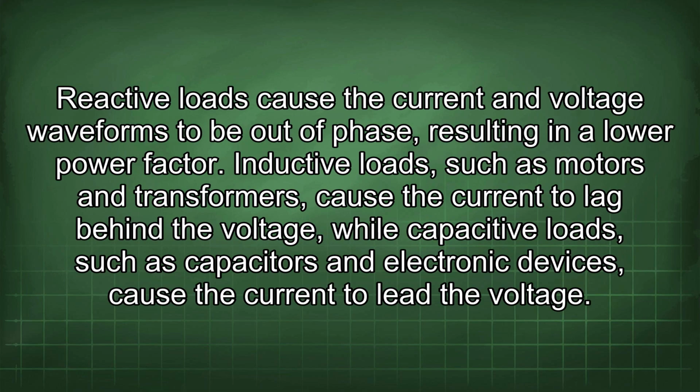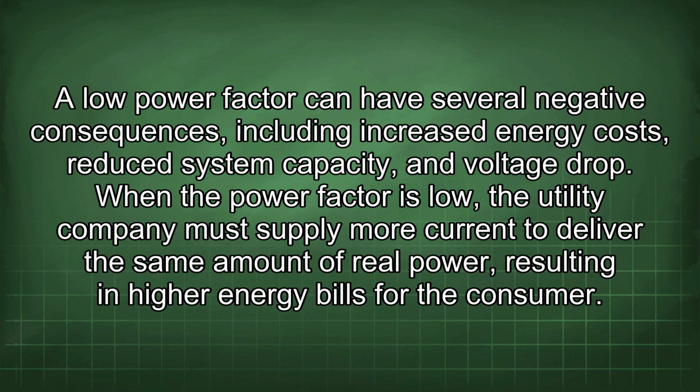Reactive loads cause the current and voltage waveforms to be out of phase, resulting in a low power factor. Inductive loads, such as motors and transformers, cause the current to lag behind the voltage, while capacitive loads, such as capacitors and electronic devices, cause the current to lead the voltage. A low power factor can have several negative consequences, including increased energy costs, reduced system capacity, and voltage drop.